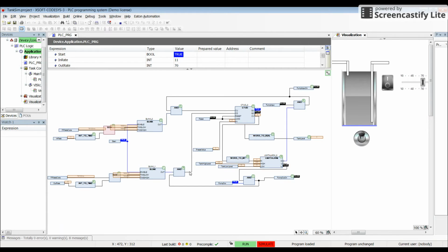And then the output of the AND here, which receives the input from the blink and the second input from here, which I will explain right now, is fed into the countdown input of the up-down counter. As a result, whenever we have the square waveform here, the value of the counter will decrease.